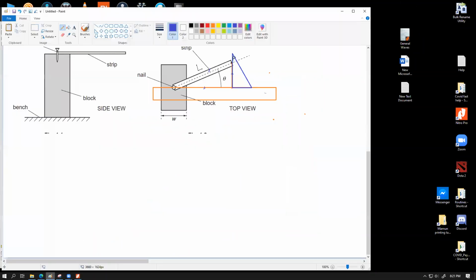For example, we can try and measure the height of the wooden strip along this place and maybe along this place, in two different places, to make sure that it is exactly equal. This will essentially make sure that this strip is parallel with the table, but that doesn't ensure that the strip is horizontal. To check horizontal, a spirit level is always the most commonly used and more accurate equipment to use, because if we measure that parallel way, then we also might have parallax error. That is why we use a spirit level. Precisely.